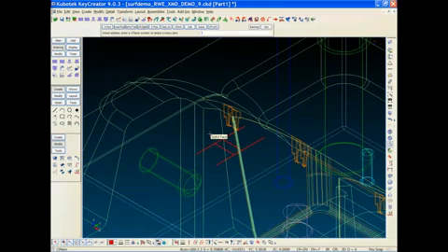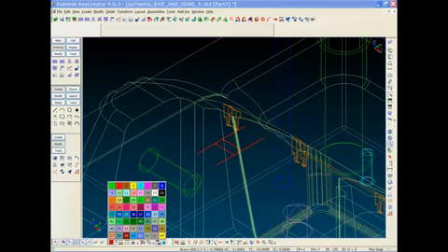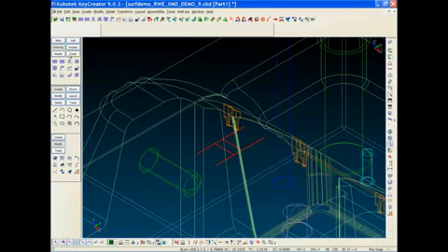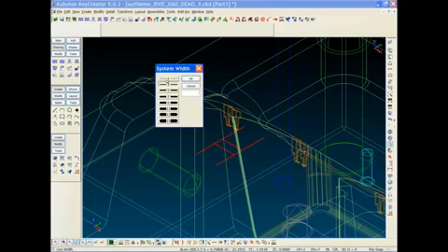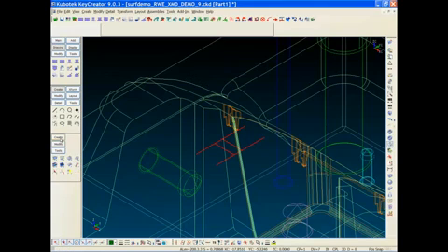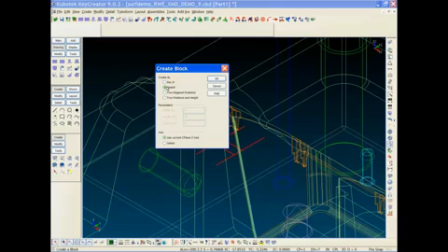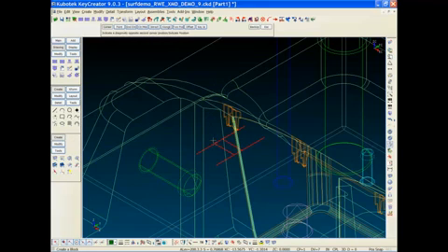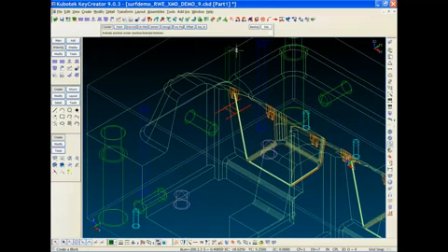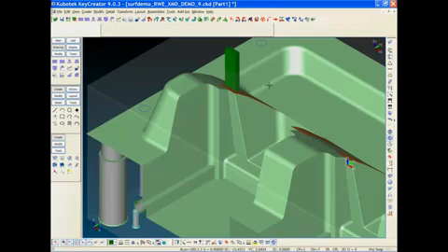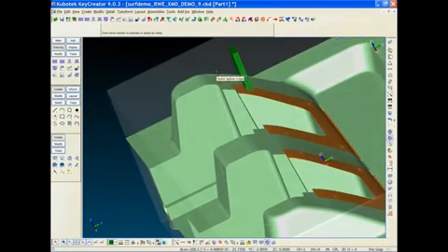Now switching over to KeyCreator Solid Modeling, I'm just going to sketch a block in here. Just going to grab the 2 diagonal corners, and I'll pull that solid up above the parting line. We'll click right there. Looks good.